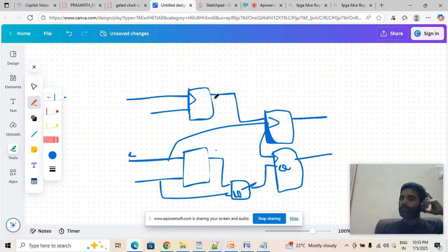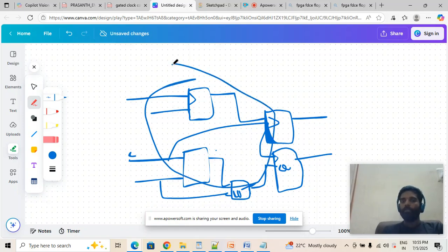So in that case, suppose your design has this kind of IPs. If you're writing a simple design, for example, any IP level development you're doing, only using this ASIC RTL, everything you're writing by pure RTL, you can directly use this tool, and the tool can understand. Just enable this clock gating option, right? And the tool will understand and convert everything, including reset logic, memory mapping, everything will be happening, right?